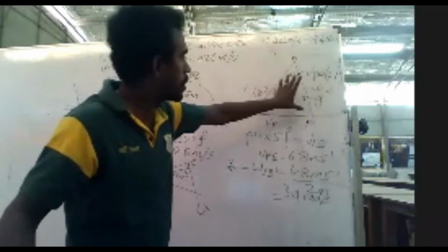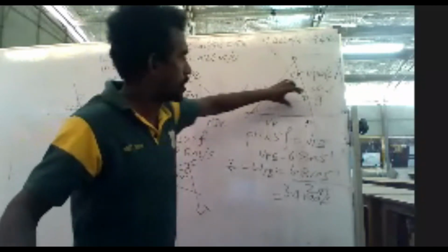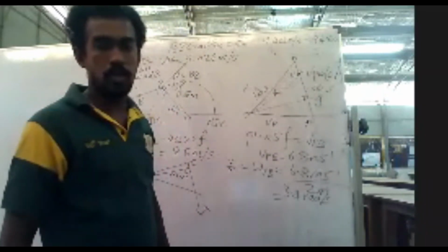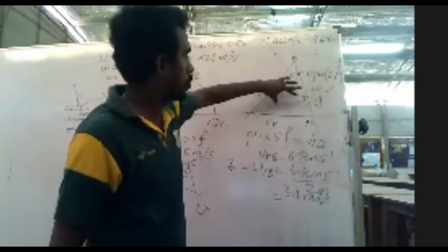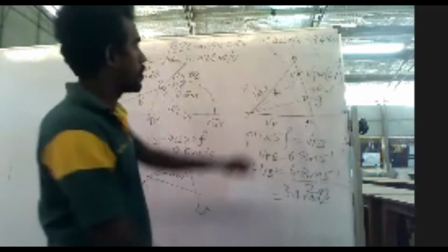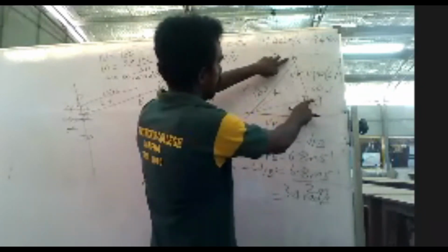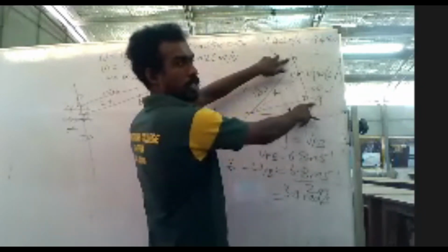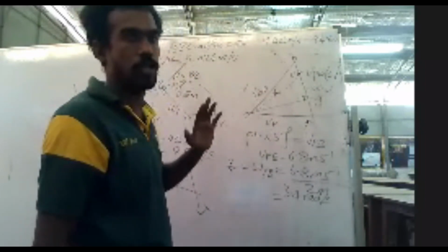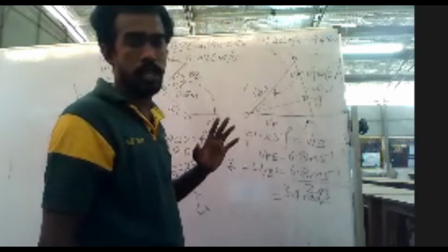So from the BP perpendicular to O, we will have the vector OG. I can measure whether I need this or this. By measurement, we find that vector Bg is 5 meter per second. You need to measure it and multiply it with the scale factor to get your final velocity. The position of point G on the connecting rod is obtained as follows.